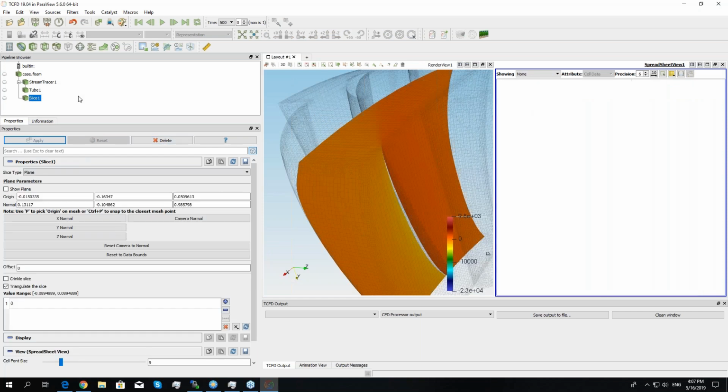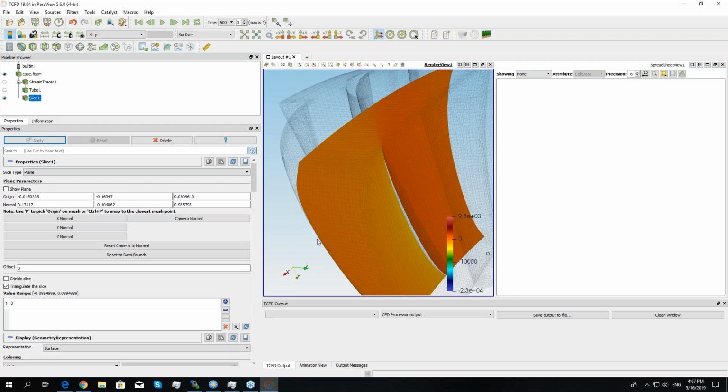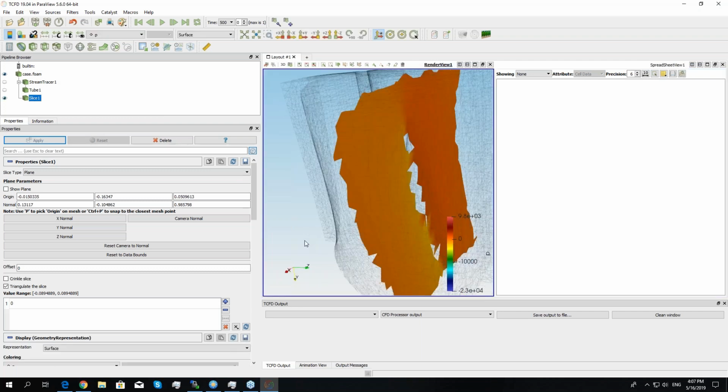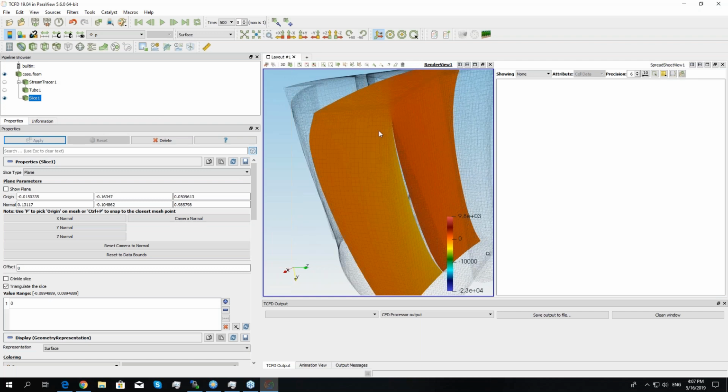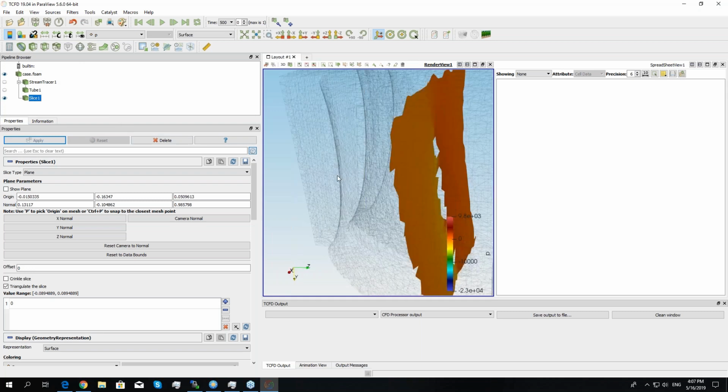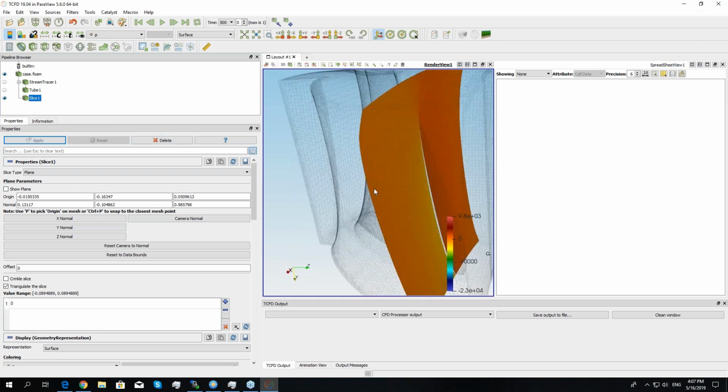If you would like to create the mass flow rate average, it is more complicated, because first you need to generate the mass flow part on each part of the slice. So first of all, we need to get the normals, because only the normal component of the velocity to your slice generates the mass flow, right, or volumetric flow.